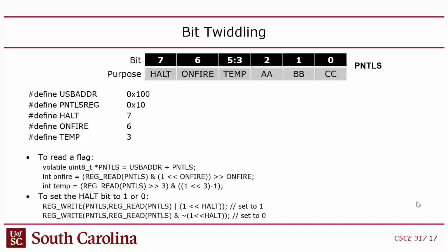Now you might say, well, that's asinine. Why not just list the addresses for each register? You could, but if you read the ESP32 technical reference manual, they actually use this format where they'll have control registers with just offsets associated, not absolute addresses, but relative addresses, right? Which kind of stinks because then you have to do the math to figure out where the actual address is, right? So what's happening is that this USB is an IP block inside the system on chip.